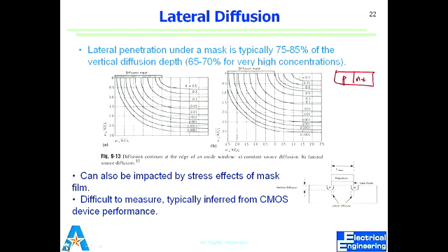Ion implantation, because the junction depth is too thin, and short channel effects are becoming very enhanced. So we don't want lateral diffusion. Because my devices are being scaled down nowadays, the junction depth has to be shallow, and because source and drain are coming too close, I can't afford lateral diffusion. So that's why ion implantation is being used.